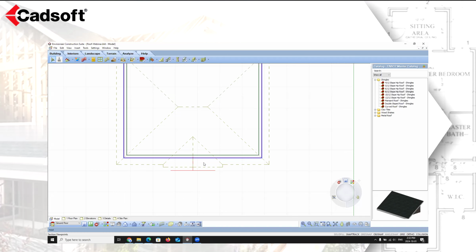Use the dormer roof tool to insert a dormer on an existing roof surface, and you can do that with either a gable edge, with a hip edge, or by creating a shed dormer. And to create a gabled portion in the middle of a fascia, you can break the roof edge at 2 points to create a new roof segment. Then you can simply select that new segment and change it to be a gable end.